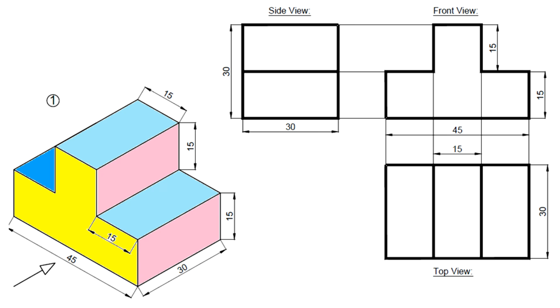Then if you go to the side view, these red color surfaces are visible, and these green color surfaces will not be visible when you are seeing perpendicular to the principal surface. So these two, because it is appearing on the right side of the object, I can get this on the right side view, but the right side view will be drawn on the left side. So take this dimension 30 by 15, and you will draw these two surfaces. So this is how you will be completing the orthographic views for this diagram.